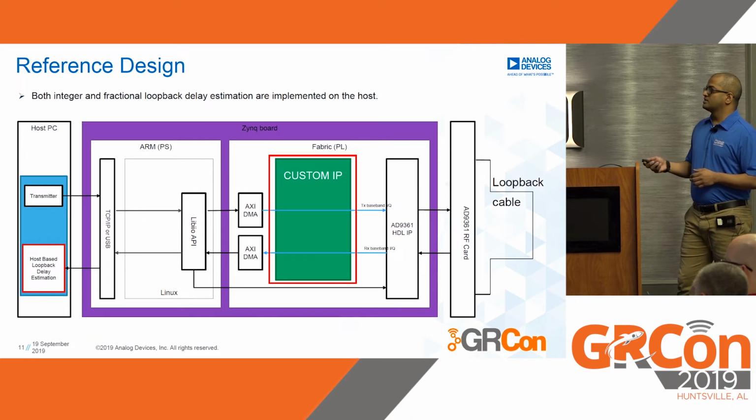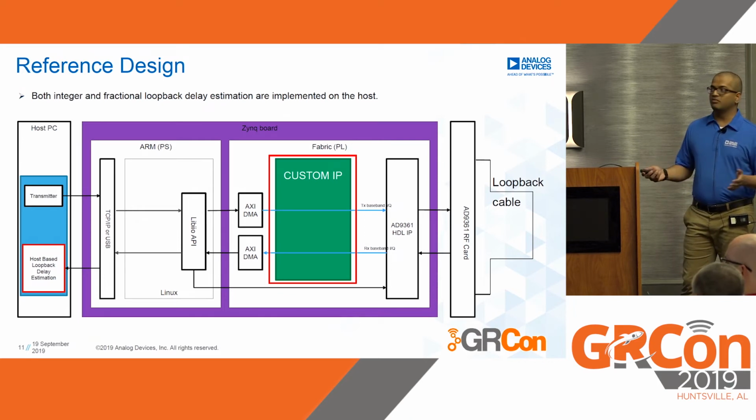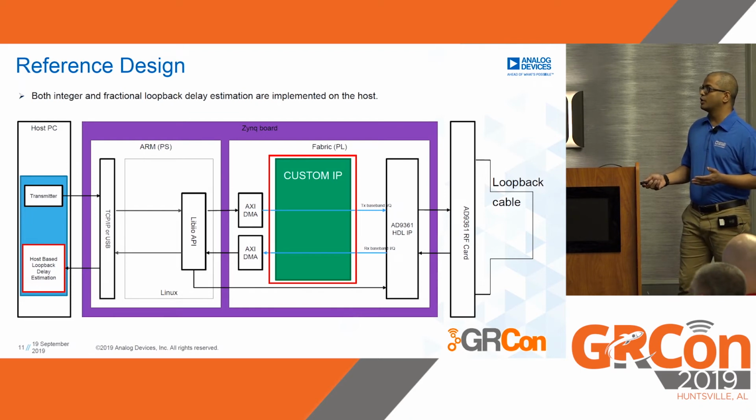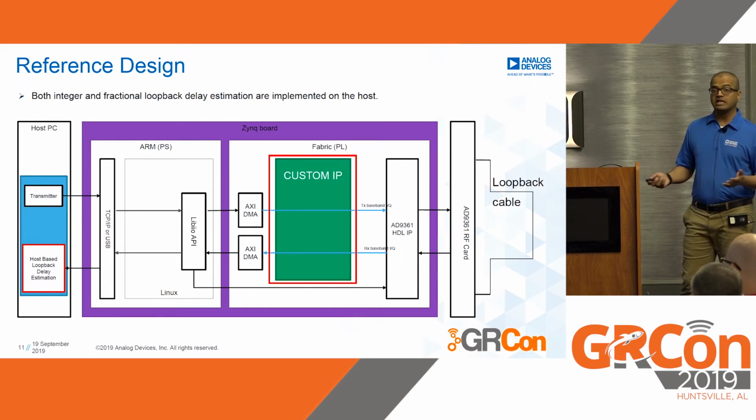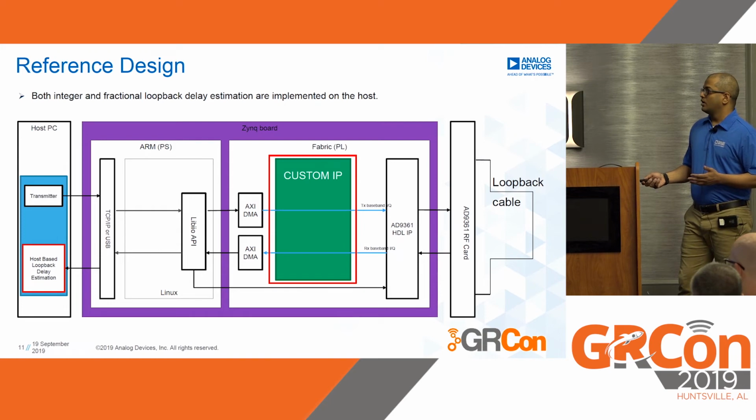So in this step 0, the transceiver is only acting as a streaming device. We send all the samples back to the host PC, and all the signal processing is done on the host PC by way of embedded Linux, libiio, etc.